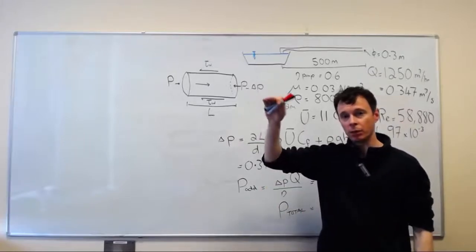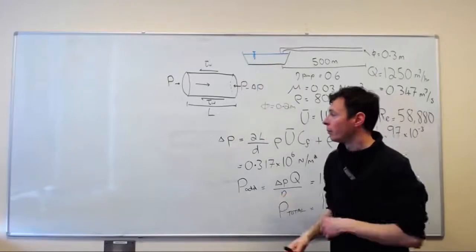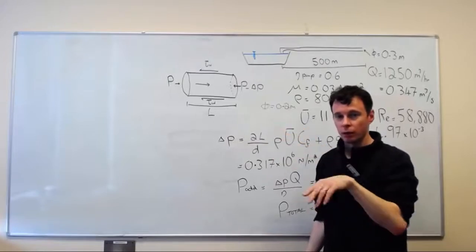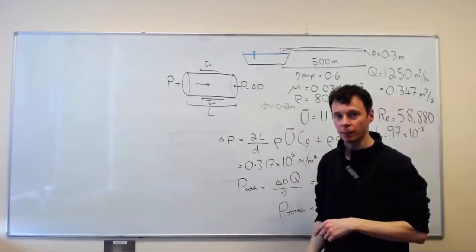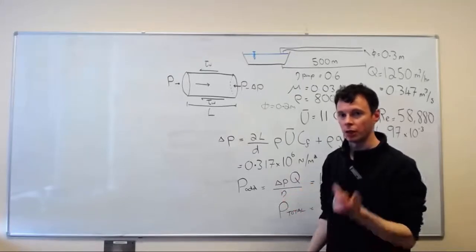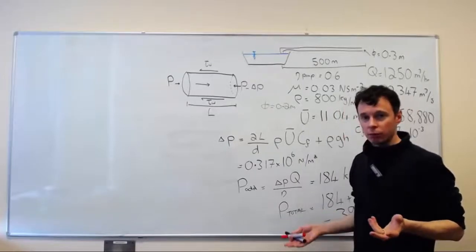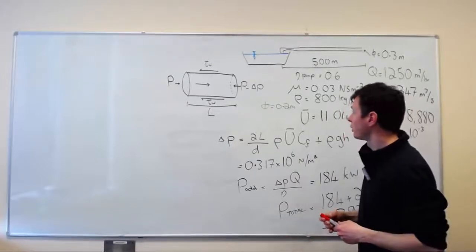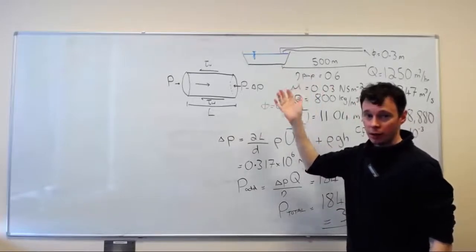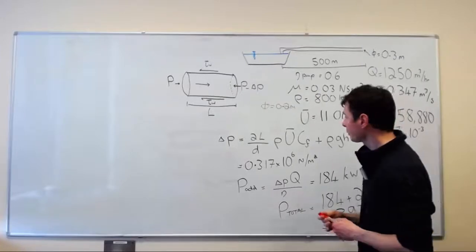And again, it's fairly high up in town, but there's some big tower blocks up on the avenue in Southampton. And again, the water will not flow out of that reservoir naturally and go to the top floor of those tower blocks. So there'll be a pump station somewhere to boost the pressure to get the water up to the top. So that's the practicalities of real viscous fluids in engineering. And we're constantly transporting fluids, oil, water, various other things, air, in such pipelines. It's an incredibly common piece of engineering.